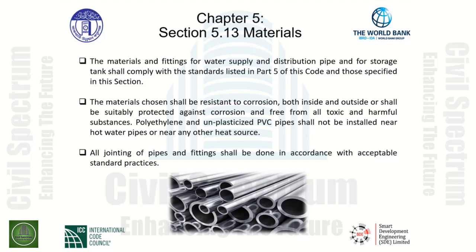Polyethylene and unplasticized PVC pipe shall not be installed near hot water pipes or near any other heat source, due to the fact that these materials will combust, they will melt, they will deform near high heat sources. All joining of pipes and fittings shall be done in accordance with acceptable standard practices.